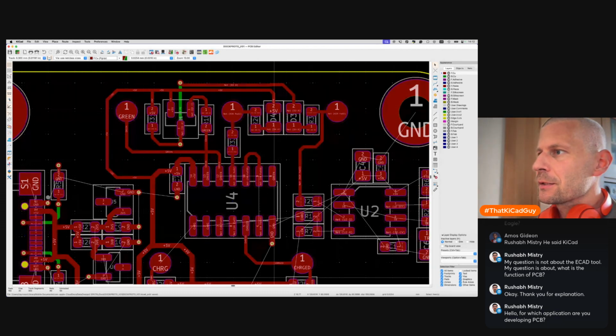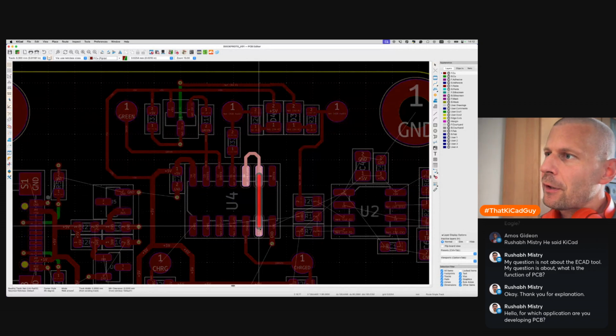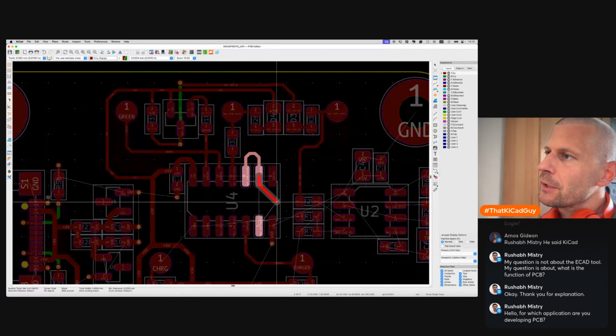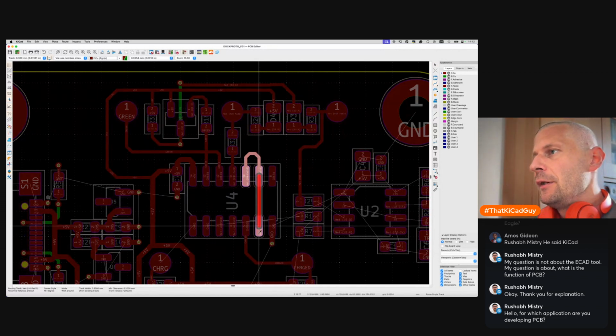You may ask why I don't connect directly below the package, the signals on port 6 and 9. The reason is, as I said, the board will be prototyping, and I will probably change the schematic a little. And when there is a track below the package and I need to cut it out, it means that I have to unsolder the package, then cut the track and get the package back.